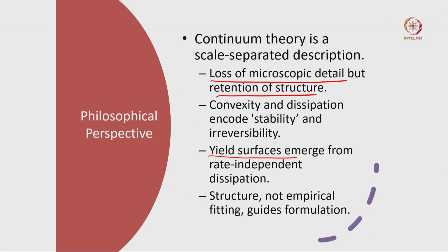The yield surface is the constraint, and the stresses produced by plastic deformation will be the corresponding reaction to this constraint. So you can think of rate independent plasticity as constrained elasticity, constrained by the yield surface. There is also rate dependent plasticity, where the notion of yield surface as a specific constraint is not there.